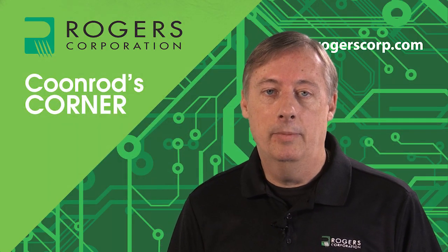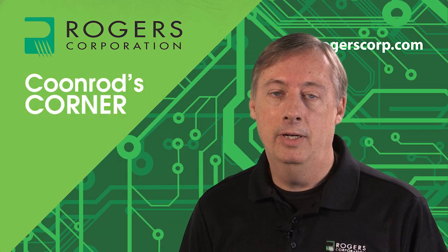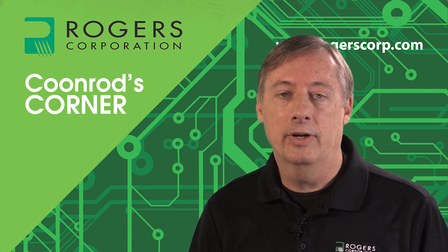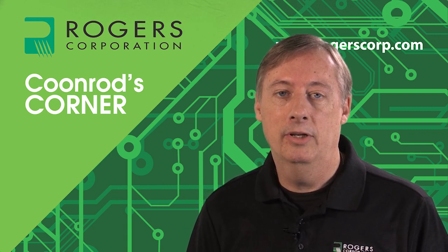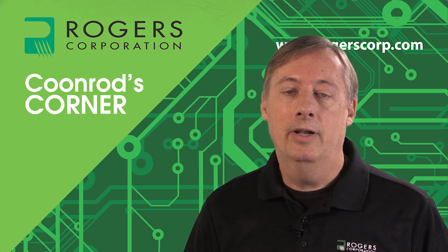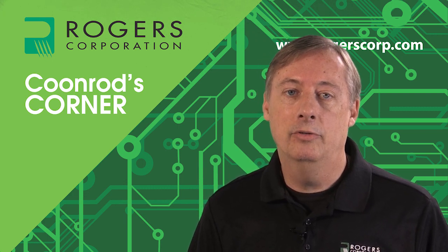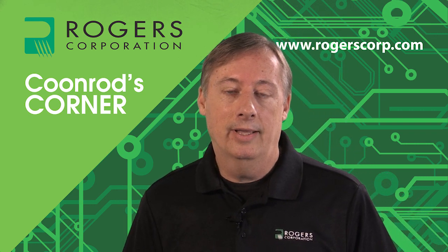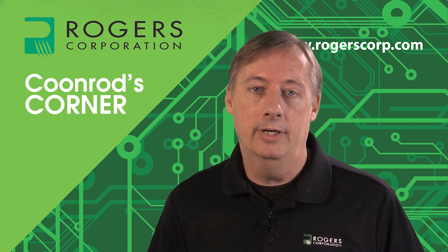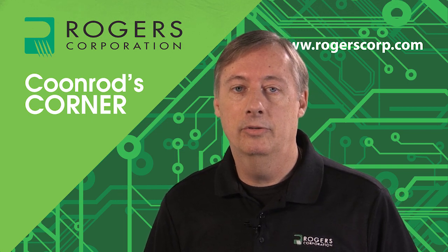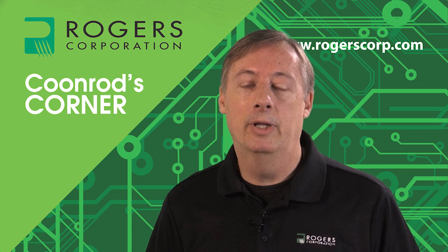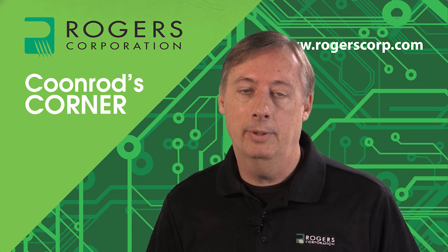With many new millimeter wave applications on the market and many more to come, a lot of RF designers are using grounded coplanar waveguide to deal with some of the issues at millimeter wave. Grounded coplanar waveguide in theory can be used to minimize or completely suppress some spurious modes, to suppress unwanted radiation, and to deal with dispersion, where if it's designed correctly you can have minimal or no dispersion for wideband applications.